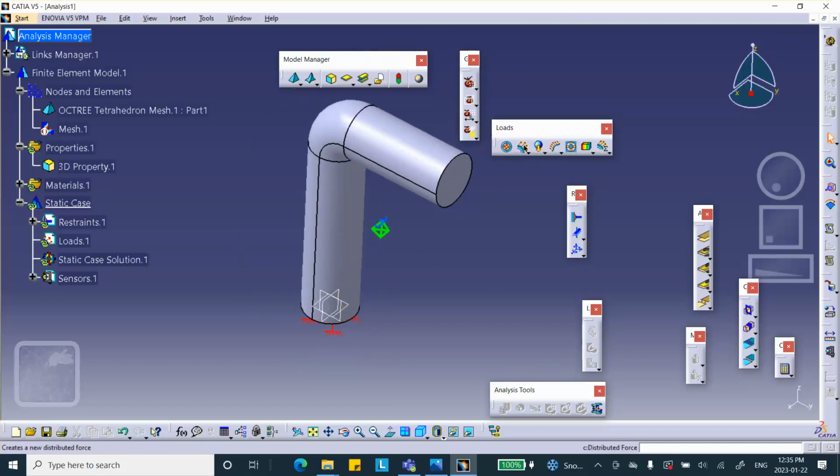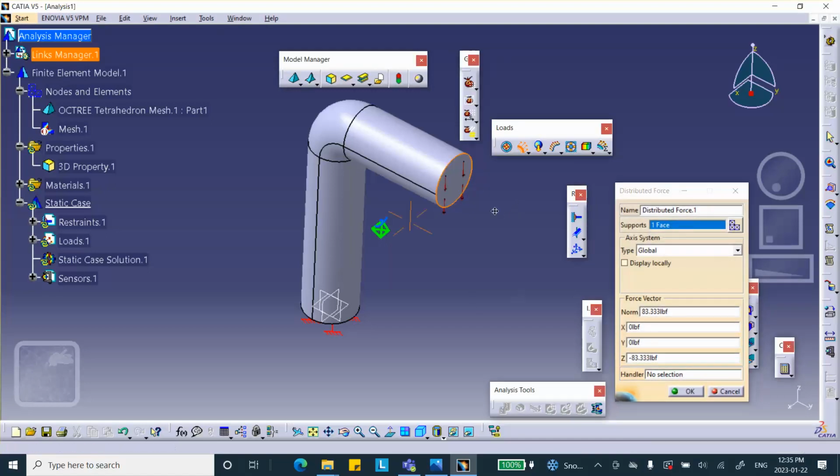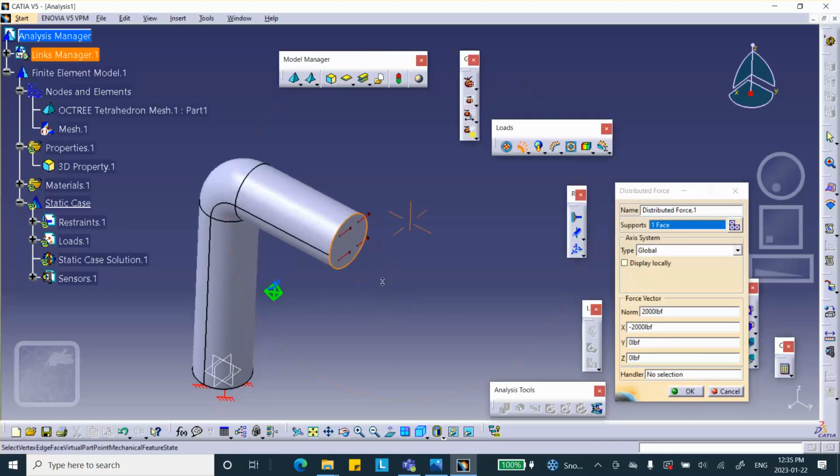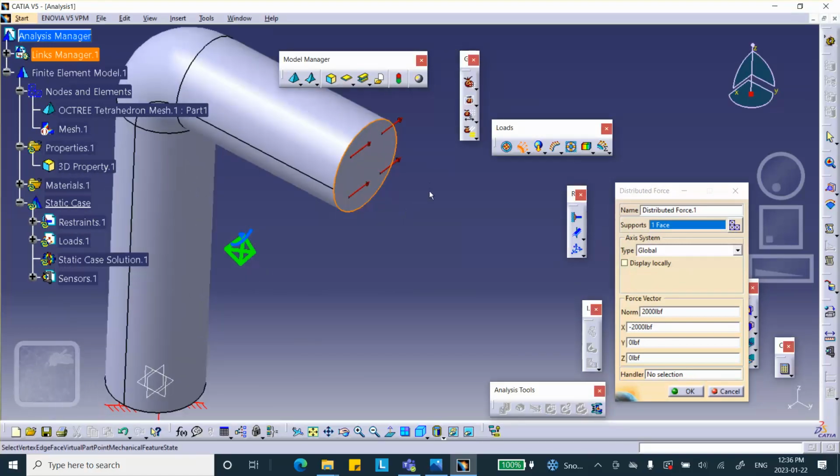And then the force, here's the force on that face in the direction X, 2,000 pounds. My units are already in pounds, and this of course has to be 0. And there we are. Now, if you want to push it in the other direction, no problem. Just put a minus sign, flip the arrows. It goes in the other direction. Now, notice that there is no plane of symmetry here. If I was applying this load in the y direction, this will bend, it will not twist, and then there is a plane of symmetry that you can use, but that's not what we have.